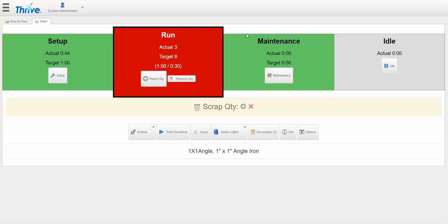So we're going to go ahead and turn off our water spider. We got our parts and we're running. You can see we're behind a little bit for the day, but we're on pace for our current cycle. So if you have long lead time cycles, you can get a better idea of what's going on. A couple other areas that you're going to notice on here, it's showing me what part I'm running at the present moment. So it's also looking at how efficient am I by each part. So if you load parts into that main screen, I now can build efficiency graphs based upon production efficiency rates by part number if I want, or on a job number.